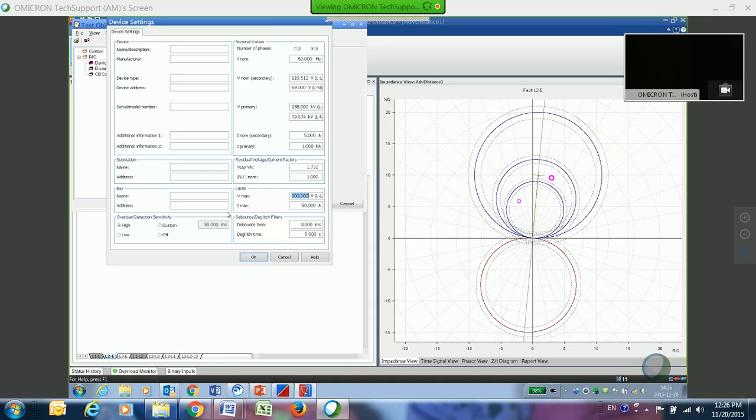And then down here I can come in and I can change my values for my limits. Maybe there are going to be cases where I want to limit my voltage and my current. Maybe we don't want to hold 50 amps on there continuous for that. And so what I would do is change that to maybe something lower, so we basically eliminate the factors of keeping that on for a long period of time and burning up our systems. But I'm going to change this as 128 amps because that's the maximum current that I can get out of a CMC 356.